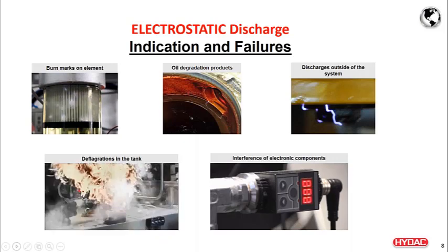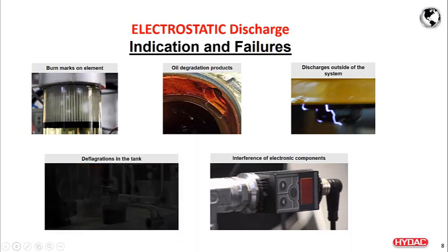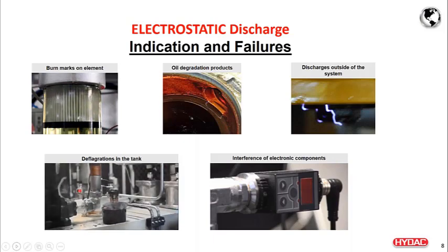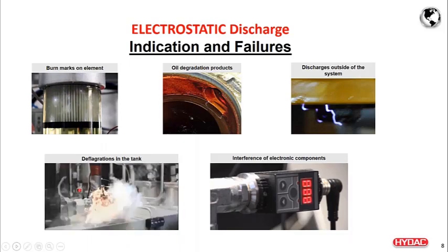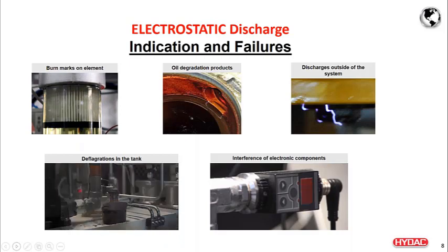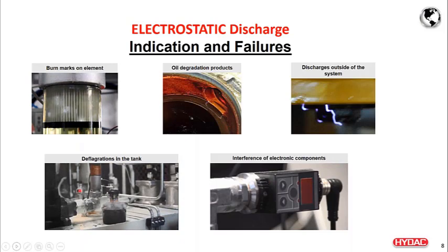Secondly, the oil degradation in the system. Third one would be discharges outside of the system, somewhere downstream of the filter housing or filter element. The fourth one here, you can see the breather is actually getting burned because of the very high charge generated downstream of the filter, which is in the tank. And the tank is one of the key components where normally the charge gets generated, and because of the oil air mist in the top of the tank, it tends to discharge within the tank, and having a breather on top of it catches fire.